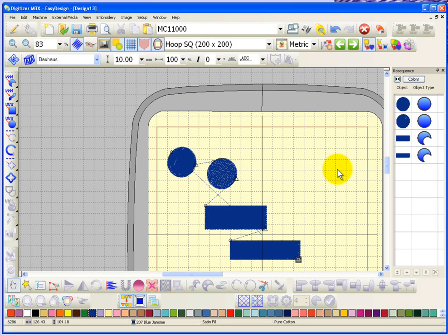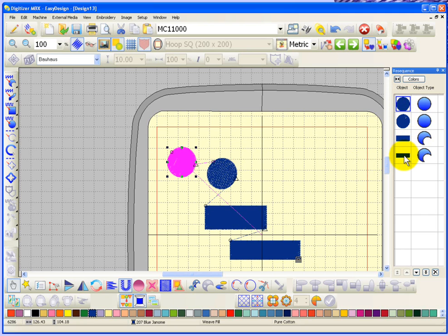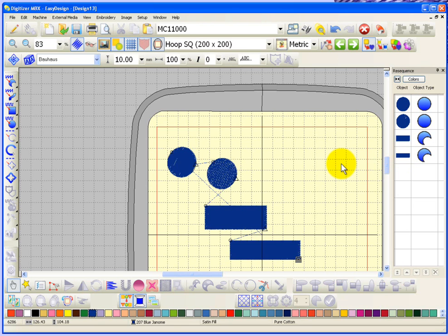You can also use the Shift key. For example, if I selected the first circle and wanted to select all 4, I could hold my Shift key on my keyboard and click on the second rectangle, and they would all be selected. So there are different ways to select objects, and there are a few more that I'll show when I talk later about the traveling tools that are found up here and how you can use those to select objects by traveling through your design. But for now, those are the easy ways.